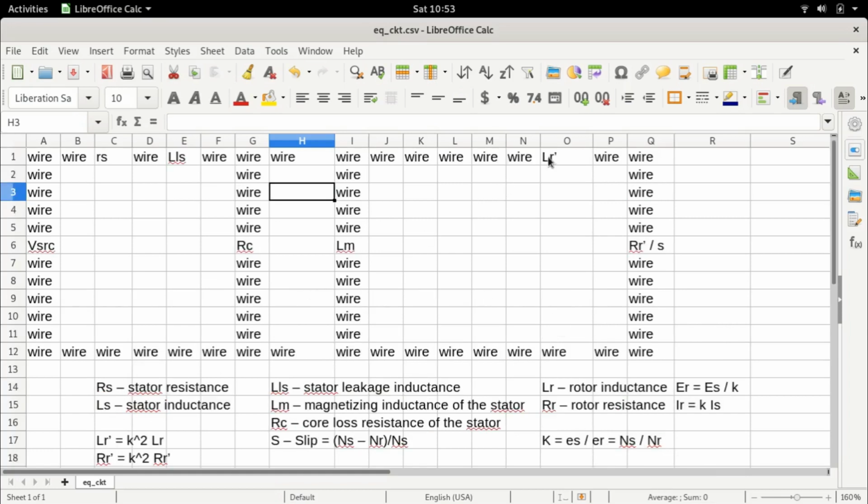The advantage is that now we have our entire single phase induction motor equivalent circuit as one complete circuit. This is not two separate circuits which are at two different frequencies. Rather, we have now merged them into a single circuit at a single frequency. It's important to note that this is for analytical purposes. Physically, nothing has changed. The induction motor is still what it is.